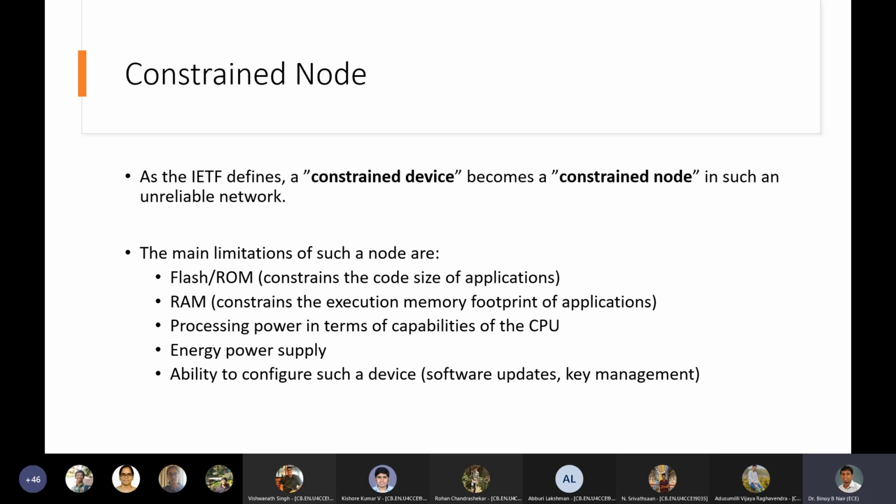Once 50 values are available in my RAM, I will take the average of that and place it there as a single value, which will filter out all the extra noise which is coming in. So the problem was that I needed 50 values to sit in the RAM at all points of time. And this is not possible if you have a Nano or something like that. You cannot put that many floating point numbers in the RAM if you have a very low quality microcontroller. I don't think it is even possible with a NodeMCU.